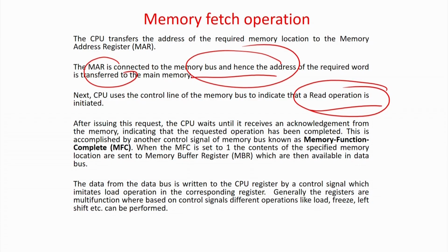So, therefore, there is a synchronization issue, that whenever I say that I read from the memory, you are never assured that immediately I will get the answer. So, there is a synchronization issue, that is a handshaking. You say that I want to read some memory location, so I give the value in the memory address register, and then the memory address register via the address bus is connected to the memory. Then you say read, so the read signal is made.